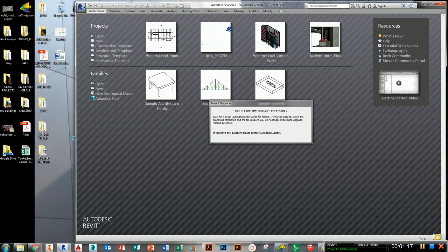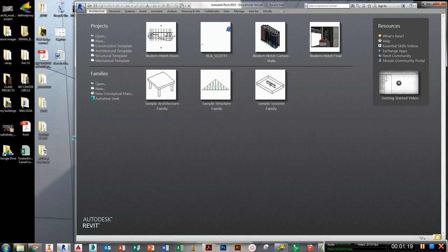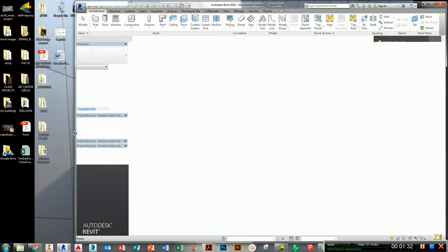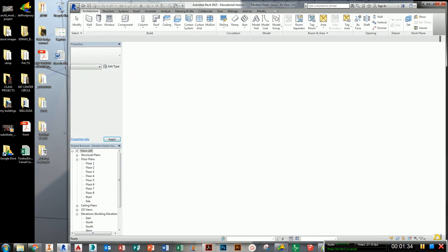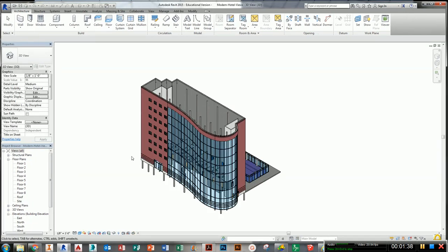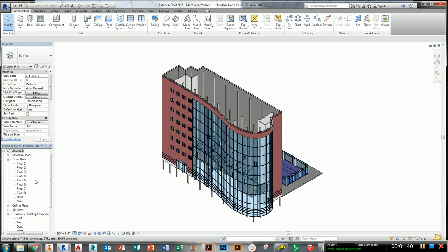That basically means we'll copy everything about the view plus the details within it. That way you get all of the settings associated with it. Now, views are really important because that's the only way anybody will know about your drawings and what you've designed. So when we create drawing sheets later on in the book, you'll see why views become really important.